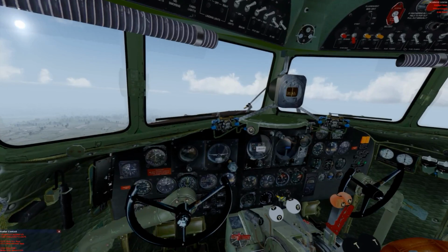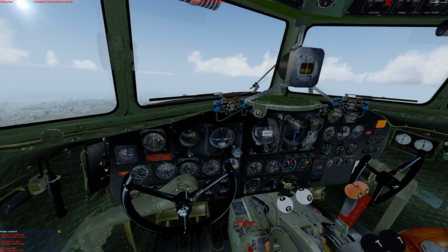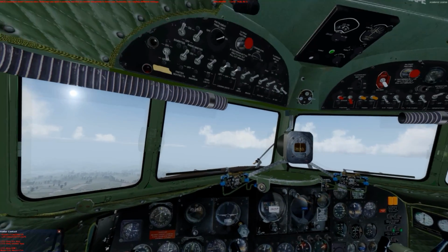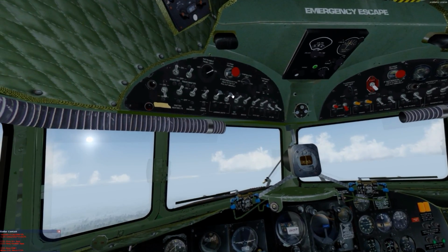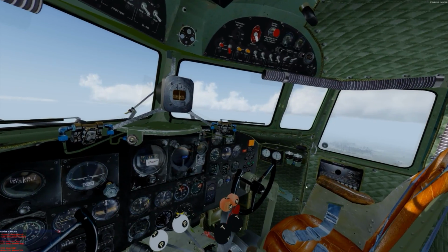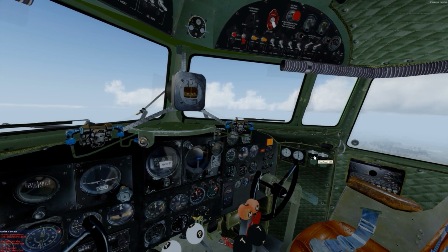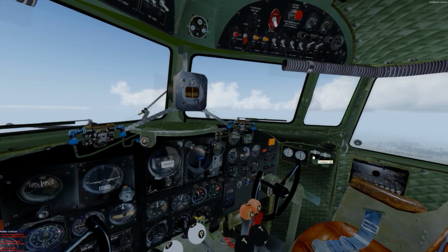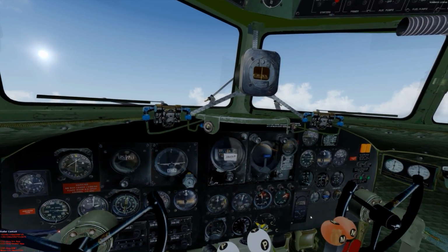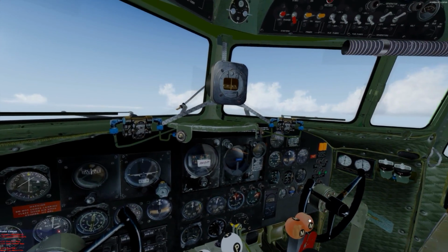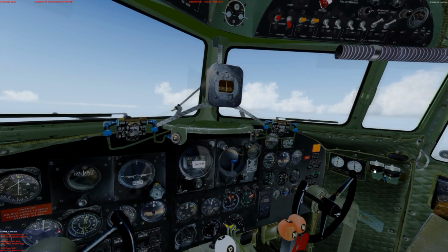Landing flow. Flaps as required. Landing lights selected on. Cowl flaps available now. Propeller set at 2450. Fasten seat belt signs switched on. Check gear down, David. Check tail wheel locked. Threshold airspeed 85. Landing flow complete, David. Cowl flaps open.